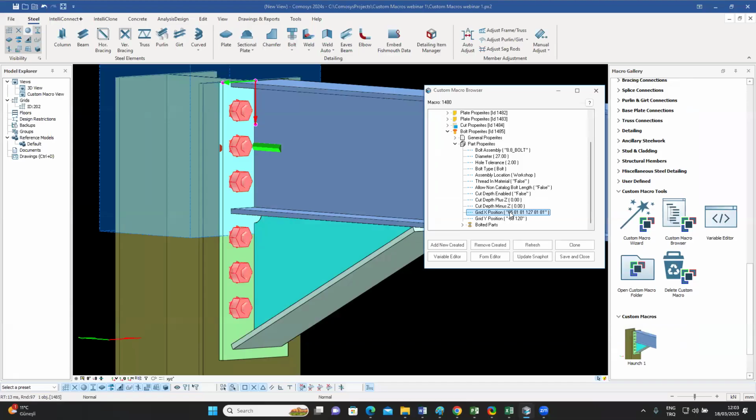So if I select on this and if I right click and I say set function, and instead of whatever it's giving me, if I say bolt dist x, I can even copy it from there as well. Yeah. And if I say okay, immediately it brings in those default numbers which I had inputted over there.